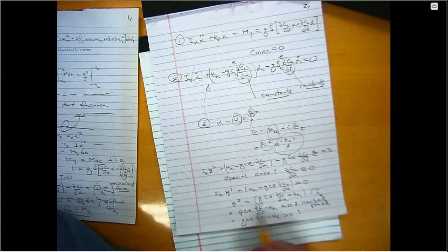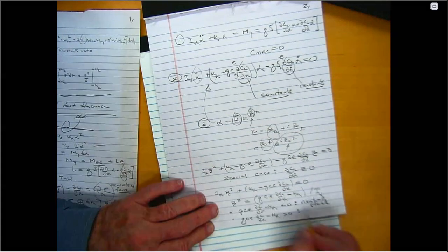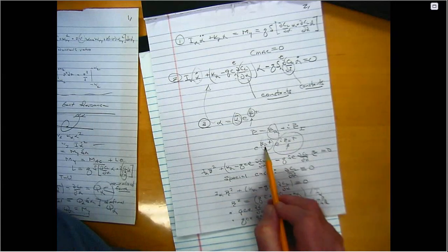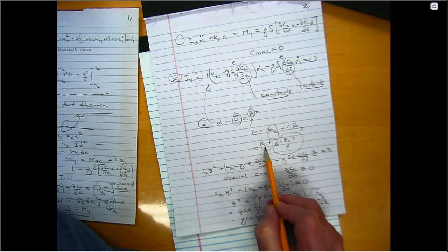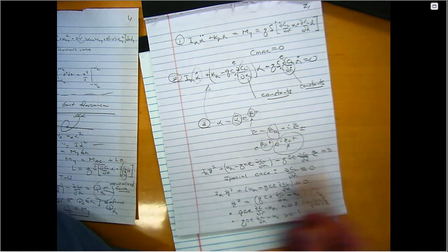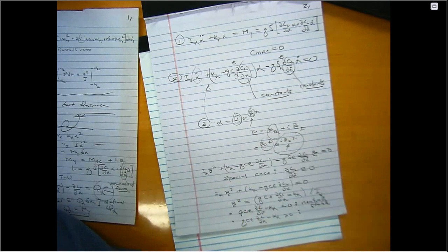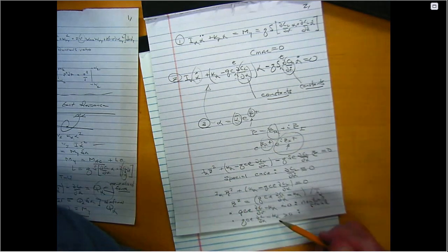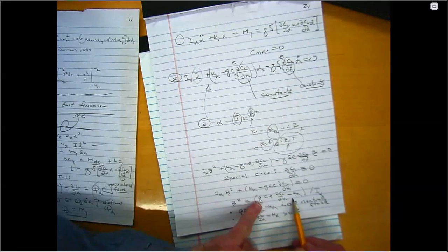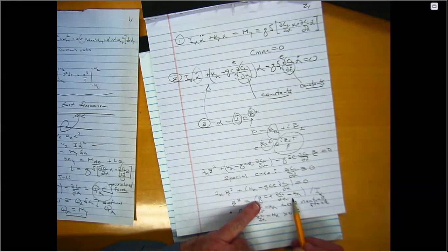then beta is either plus or minus a positive number, which means if I go back here, I have two solutions, one of which is growing exponentially with time, and one is decaying. If I let time evolve, the exponentially growing solution will dominate. In fact, according to this model, it goes off to infinity. This is an unstable system. That's divergence from a dynamics perspective, because when this coefficient is exactly 0, that is the divergence condition we saw from our static analysis.